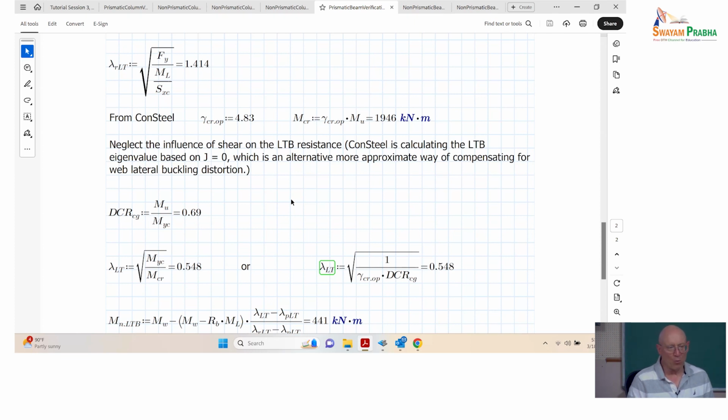We're moving away from that to always calculating the elastic buckling resistance with both St. Venant torsion resistance, GJ, or I guess it would be GIT for you, is that right? And G is the shear modulus, is that right? Okay, all right. And the warping rigidity, we call it ECw, you call it EIw, is that right? Okay. So all those terms go in, we calculate the strength.